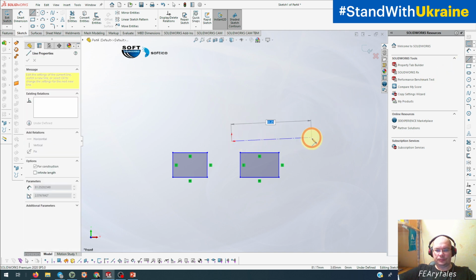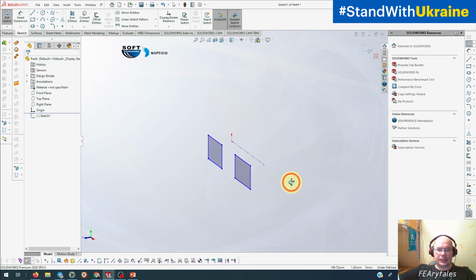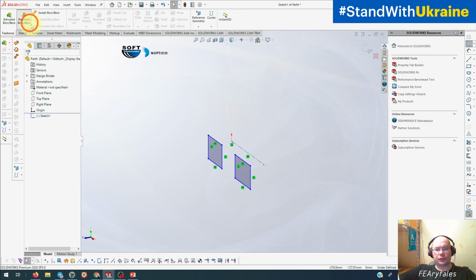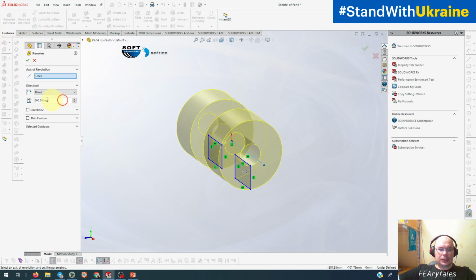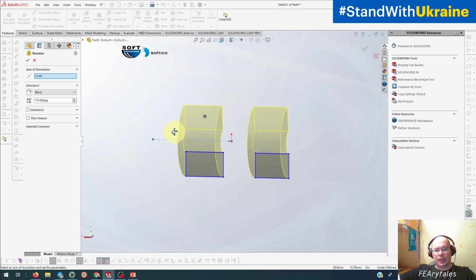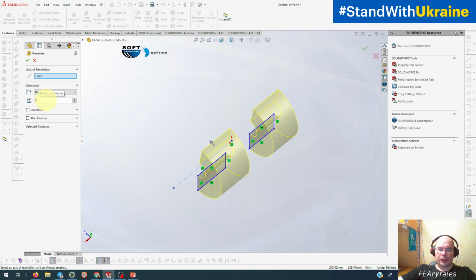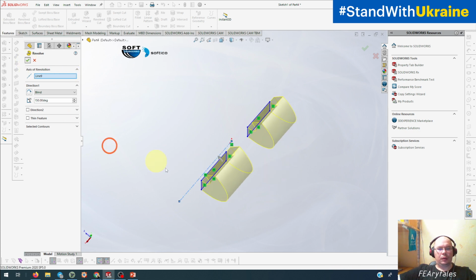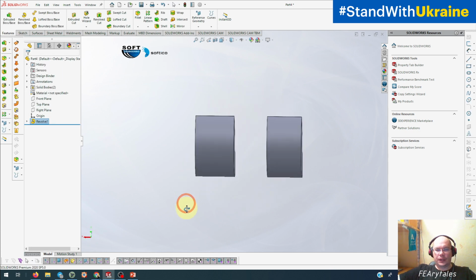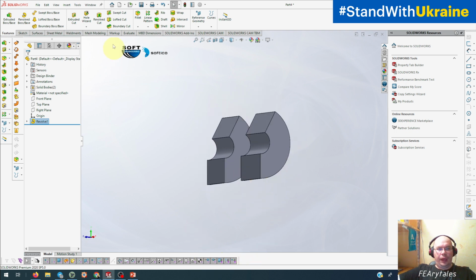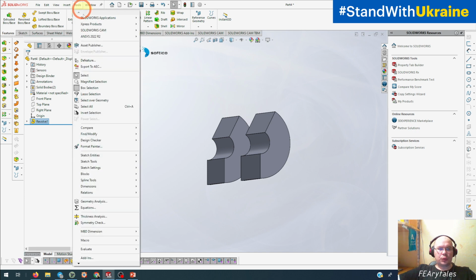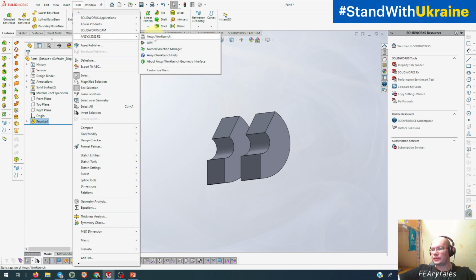It's not very important. I draw an axis for revolving, and I use revolve to create 170 degrees. Sorry, 170 degrees. Something like that. Maybe even 150 for better viewing. Okay, we have this geometry, and we can send it to Ansys with Ansys Workbench.